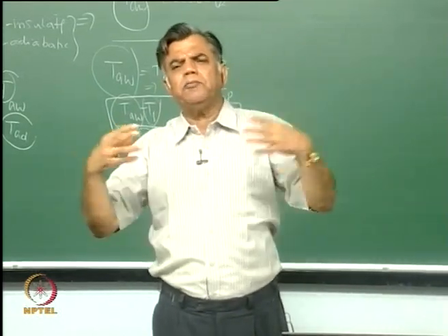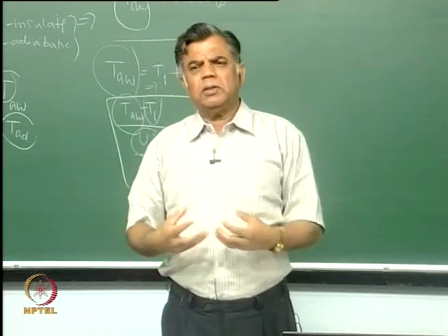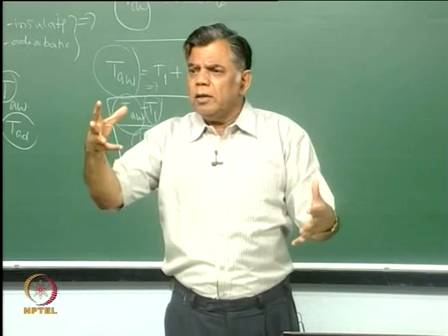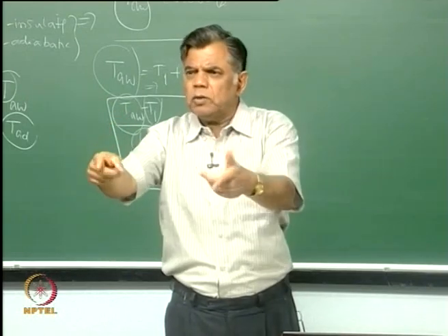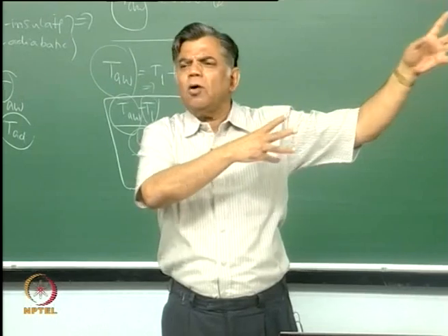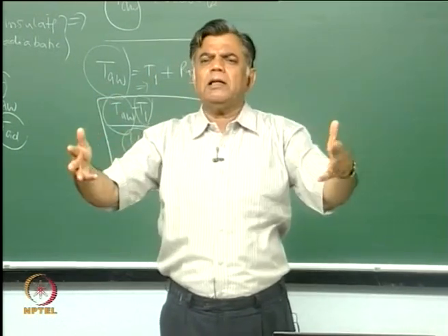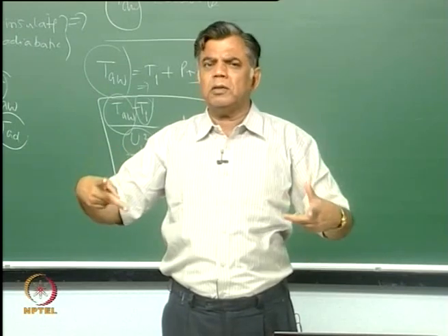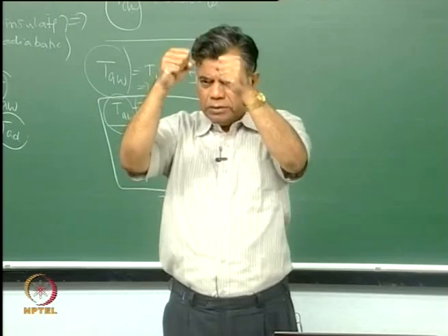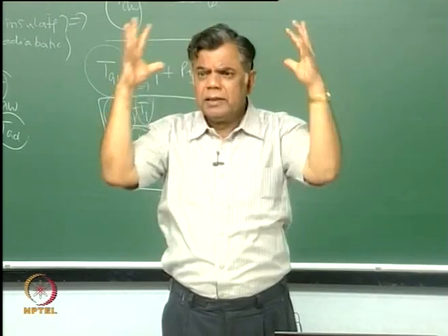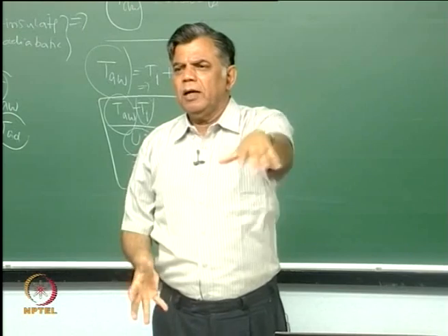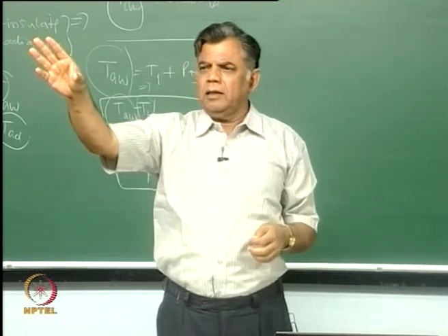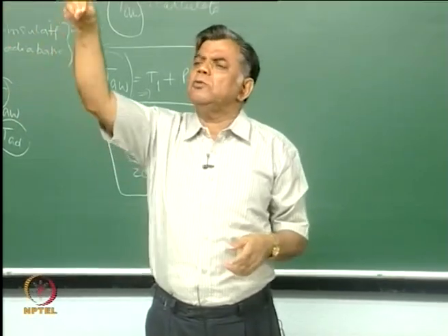All these new ideas: the physics of the problem, how to solve the convection equation, how to put in the boundary conditions and actually solve. Now if you take a complex Navier-Stokes equation, you won't do this; you will go to a code that you won't know how it is done. You have now integrated every equation, the temperature equation twice every time, to get the two constants depending upon the two boundary conditions. So the whole thing about convection is encapsulated in this Couette problem. If you know this problem completely, you can play with any equation. Even if you go to the code, at least you know what is happening.